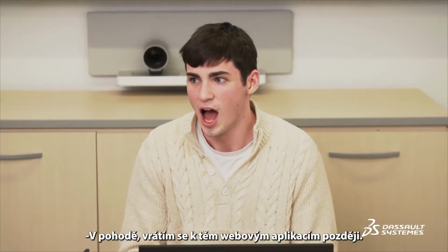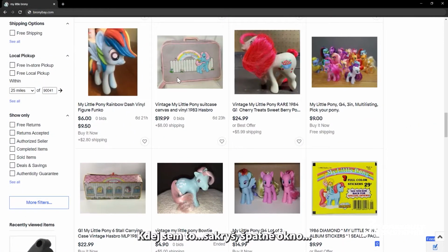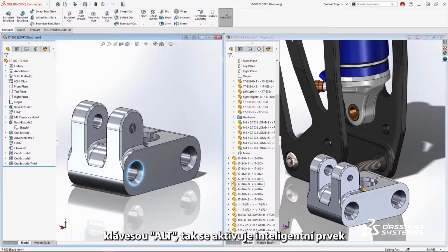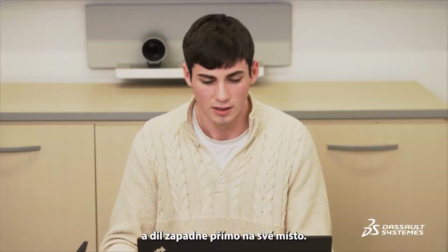All right, I'll come back to those web apps later. Where was I? Whoops, dang it, wrong window. Okay, back to the bracket. So, we can take this and just drag it into the assembly. And if we click this edge and hold the Alt key, it turns on SmartMates and snaps right into place.